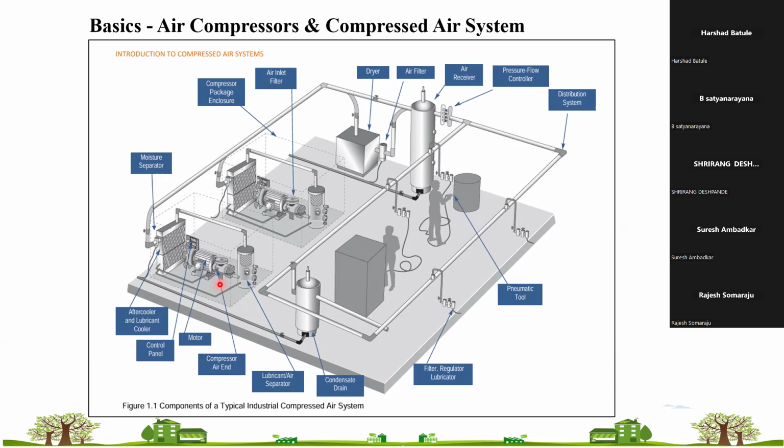So let's say 10 seconds are used for the load cycle to reach from 6 bar to 7 bar, and from 7 bar to 6 bar, the unload cycle, 1 minute is consumed. So 10 seconds and 60 seconds. 10 seconds is your load cycle, 60 seconds is your unload cycle during leakages.